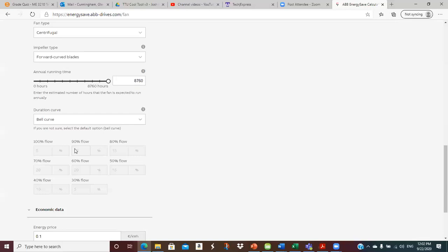Well, if you got 75% steam production, you should need someplace around 75, 80% of your fan capacity. And in reality, the fans are usually oversized significantly. So even at full load, the fan has more capability than it really needs because they don't want to wind up short on air. So they usually upsize the fan on these things.